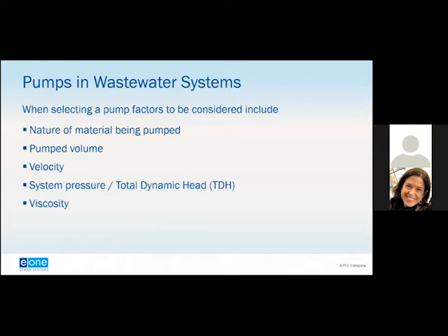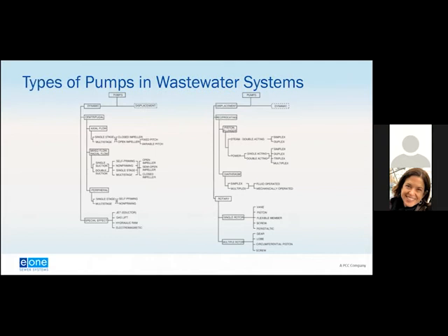For macerated solids in water, it is also going to be typically zero. But if you were pumping something like a sludge or some other chemicals or a polymer, the viscosity becomes an important consideration when you're looking at a centrifugal pump versus a positive displacement pump.